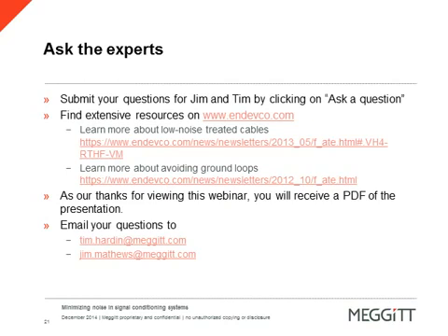Oh, okay, so I addressed that a little bit earlier in the presentation, and the contrast here is looking at the case of the accelerometer and how the low side of the accelerometer sensor output, the crystal output, is hooked up. In the first instance, we have the low side connected to the case of the accelerometer. Okay, that's one point. On the second one, it's isolated. It's not connected to the case of the accelerometer.